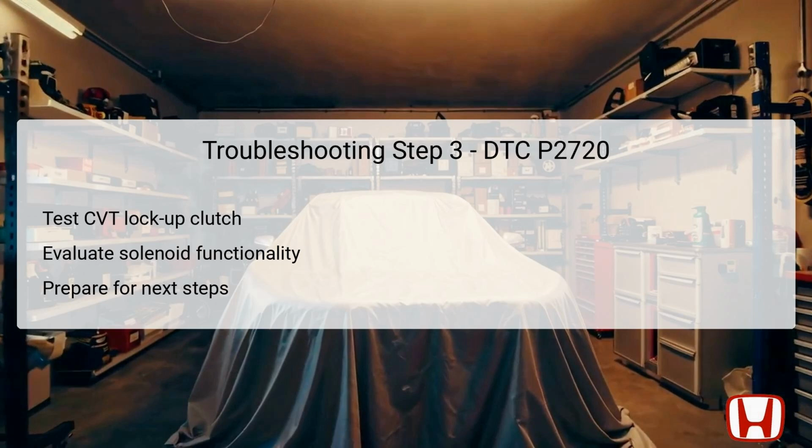Understanding the proper operation of this clutch control solenoid is essential because it influences the efficiency and responsiveness of the vehicle's transmission. If issues arise here, it can lead to further complications either in the lockup function of the CVT or erratic shifting behaviors. The results from this step will direct you to either proceed with further electrical checks or possibly tackle actual component replacements depending on functionality.